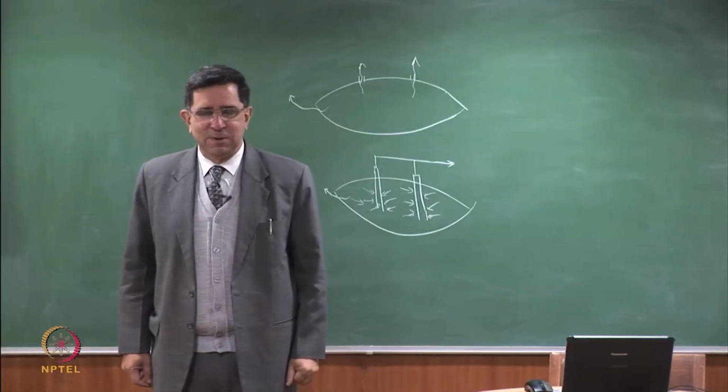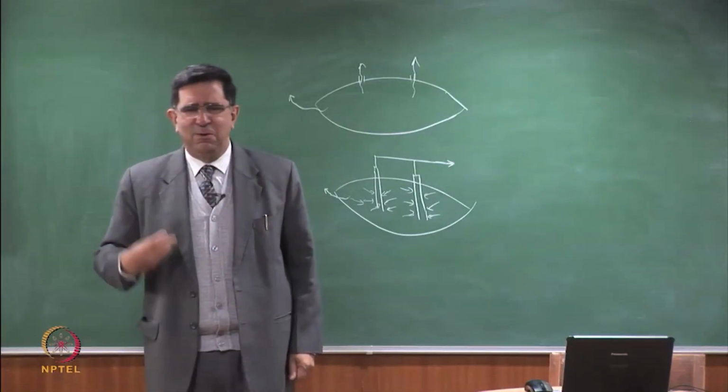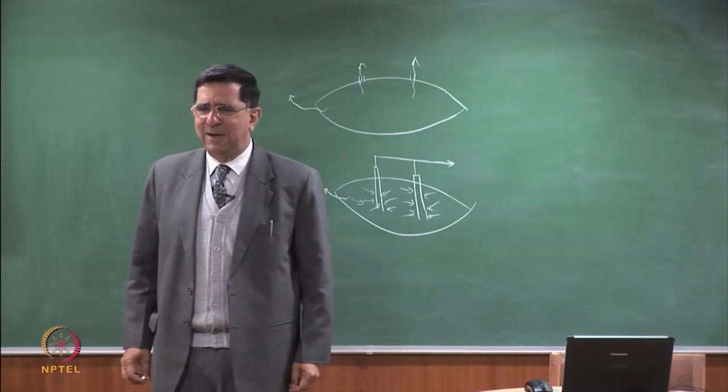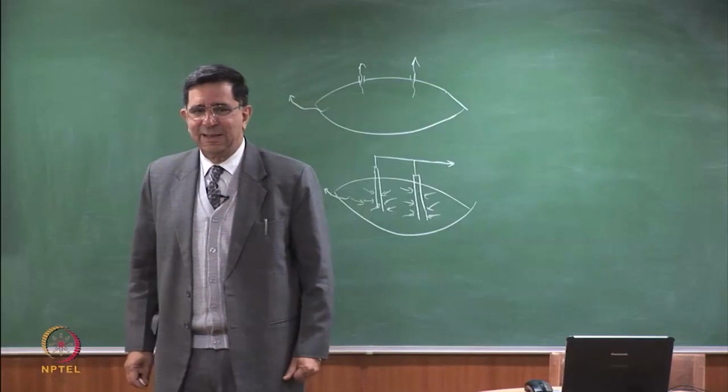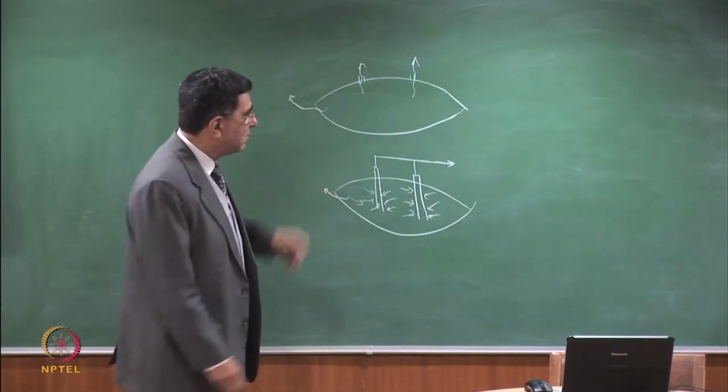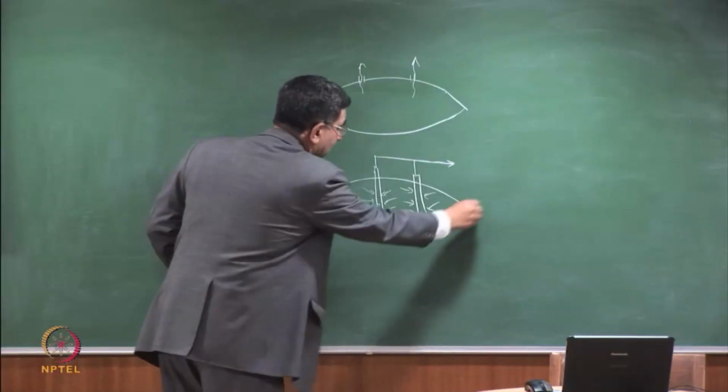You will tell your pump operator, thoda aur section lagao. Dada, thoda aur, put more suction. Let's get more gas out of it. Let's get both of you and I get bonus. What will happen? Well, if your liner and cover is not good enough, air is going to start coming in.